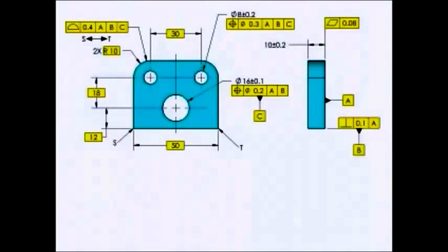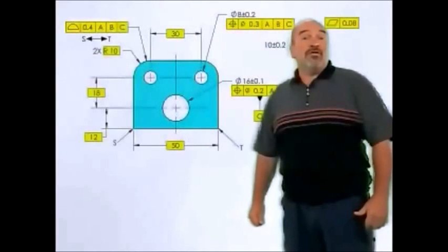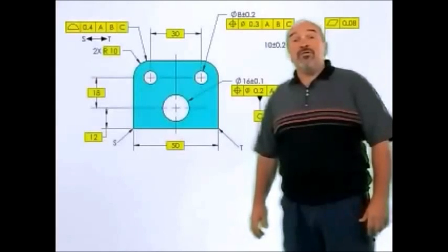Since the dimensions are basic, they may be placed on the drawing any number of ways without changing the meaning. In fact, with the new ASME Y14.41 standard, dimensions often may not even appear on the drawing.